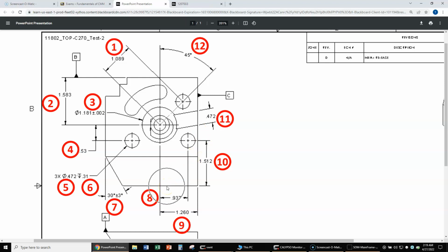So we could put just a point on the front of the part to output balloon 10 because we're taking advantage of the Cartesian coordinate system. We're locked into an x, y grid that are perpendicular. However, this slot here is on an angle. We don't know what that angle is. So we have to have a line on one side of the slot so that we can shoot off of that line perpendicular. So in this case, we want a line with a minimum of 2 points on one side of the slot, doesn't matter which. And then we could have either a line or a point on the other side. In this case, I'm going to do a line on this front side, and then I'll do a point on the back side.